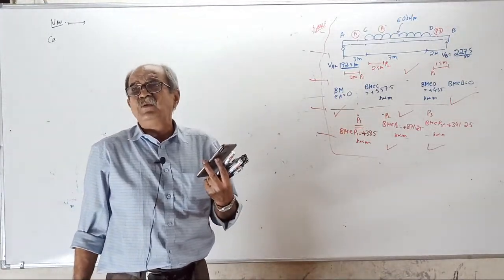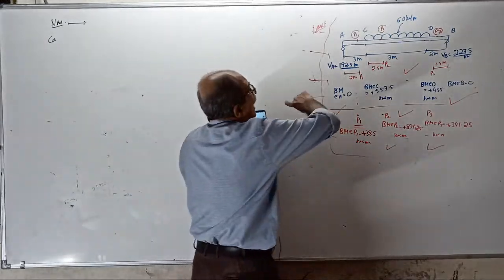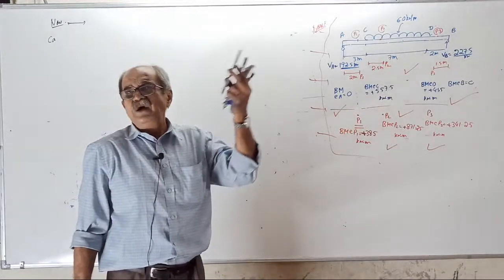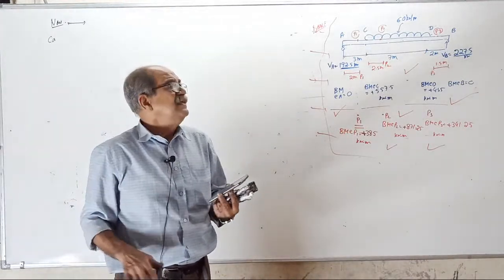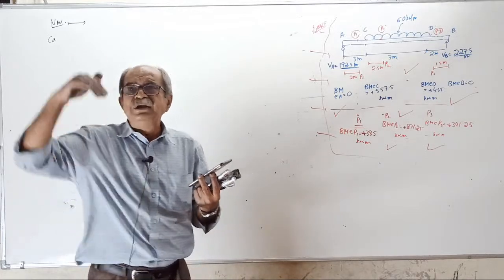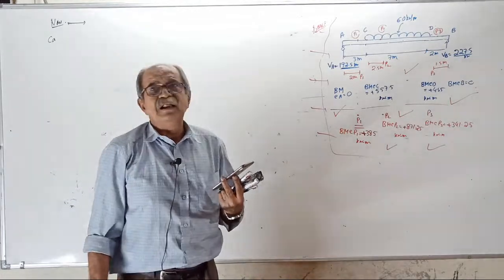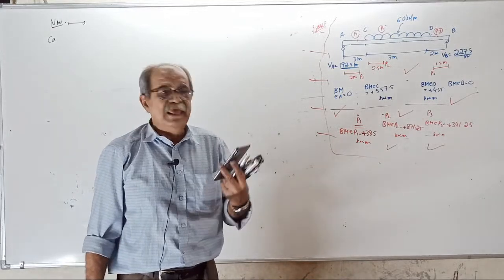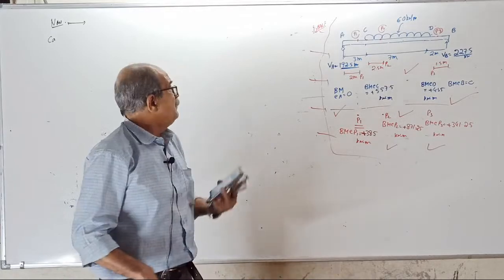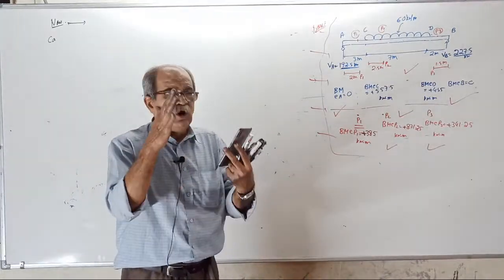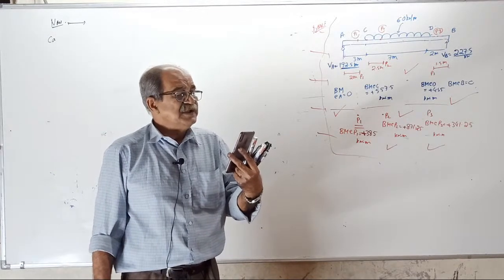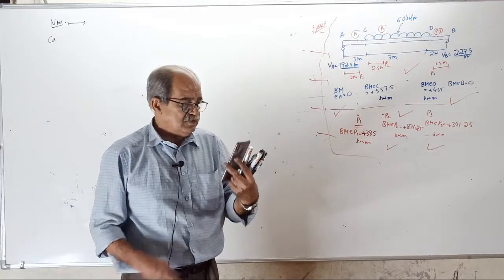Then using that equation, find bending moment at all these points. If bending moments at all the points are tallying, then that mx equation can be used to continue the question for further, that is integration. It is ready for integration. Clear or not? See, if that equation is wrong, you cannot go for slope and deflection. If the equation is correct, then you can proceed further.